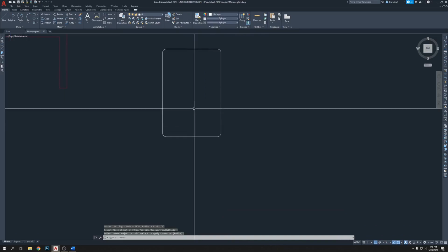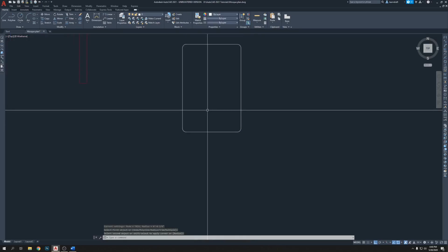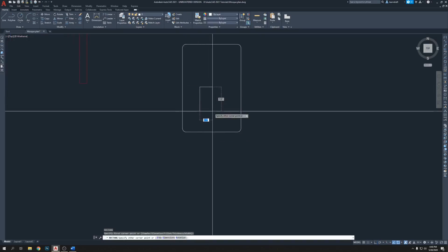And we need to place the glass. REC, enter, click D, enter. Oh, glass is going to be 1 inch thick. So let's say yeah, it's supposed to be 1 inch, but maybe they wanna use single glass. If they use single glass, it's not going to be 1 inch thick. So make it like 1/2 inch, 0.5, enter, 0.5.